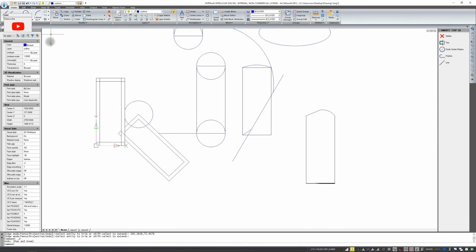If you draw and you do not have Ortho turned on, then if you press Shift, the Ortho turns on automatically. Now please note, if I have Ortho on and I turn on Shift, it won't work for a while. So remember, Shift is a special button that changes our options a little while drawing or editing, and it comes in handy very often, so I suggest using it.